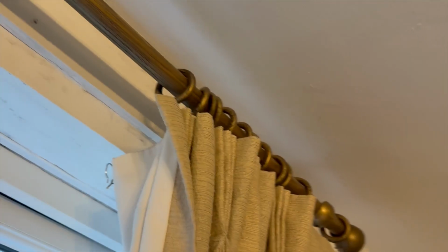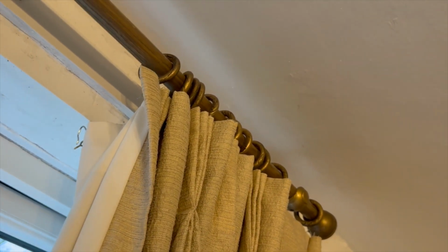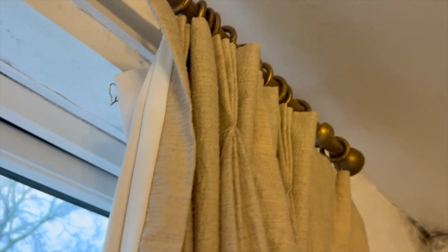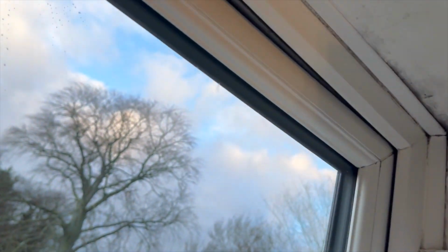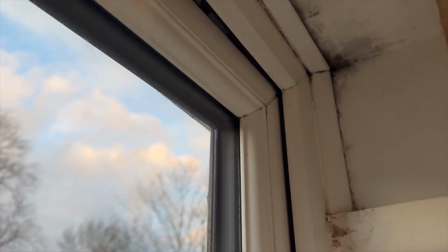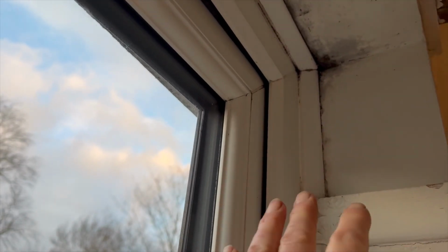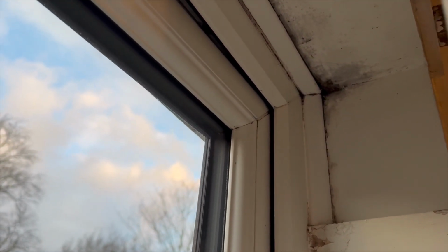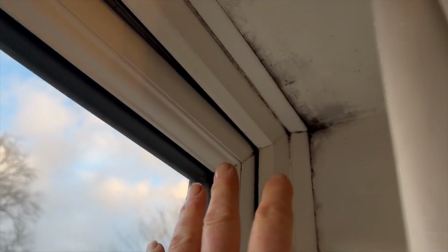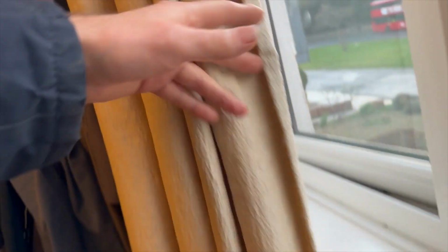Then the third thing is the airflow is reduced by curtains, which obviously you need to have, but it's just a factor. Also into the recess, into the window reveal, as it's called here. So that slows the airflow from the radiator. You're drying clothes on the radiator, which obviously is producing extra vapor as well.